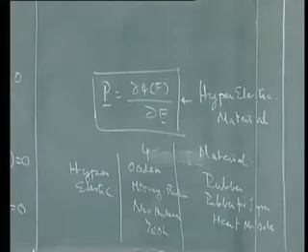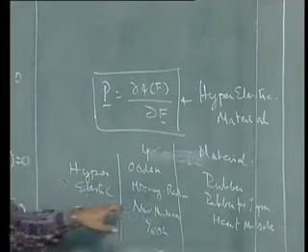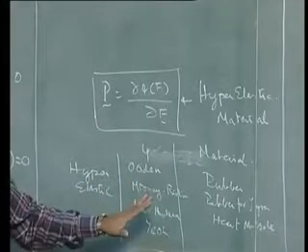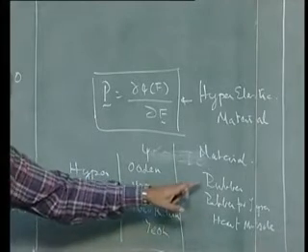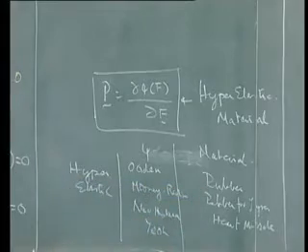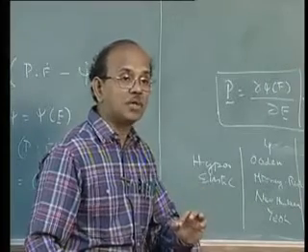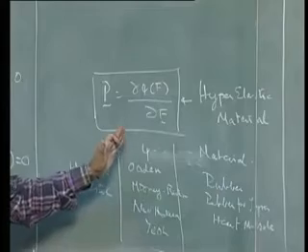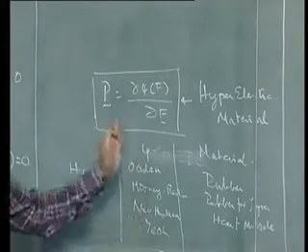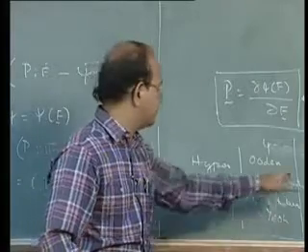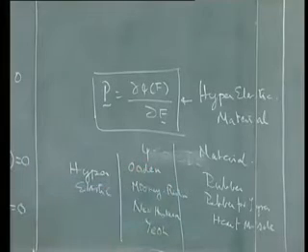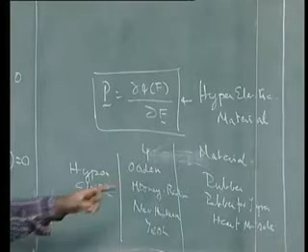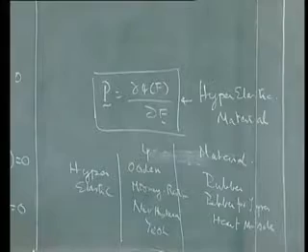The big picture is all of them are of course hyperelastic materials. The second picture is that each one of these materials can be represented as one or more of the middle column of materials. Rubber can be represented as Ogden material, not very accurately using a neo-Hookean material.